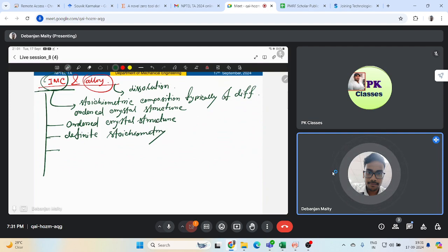They can have different bonding characteristics: metallic, covalent, or ionic character. In terms of melting point, because you have an intermetallic formation, they will always have high melting points compared to the parent metals.